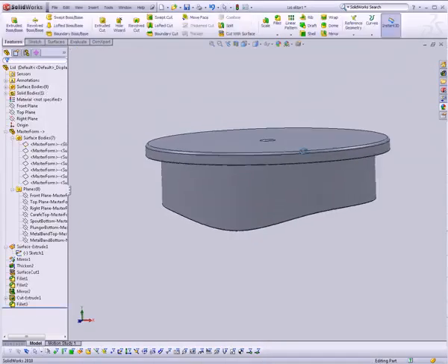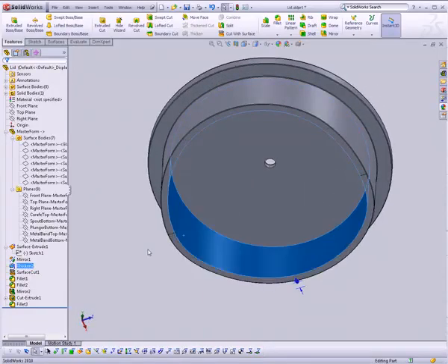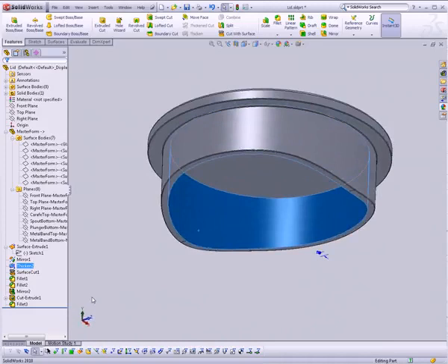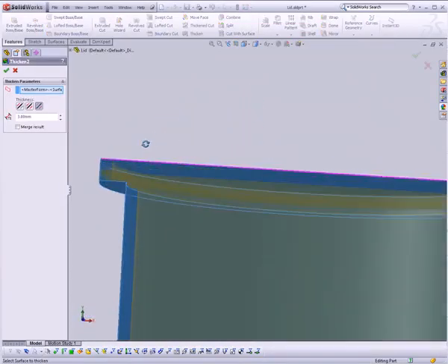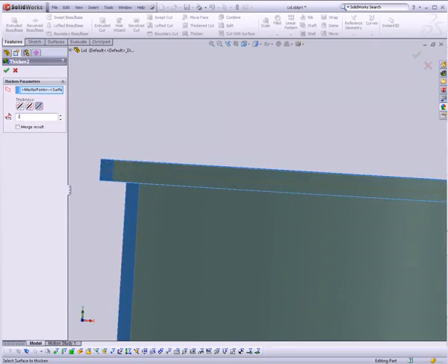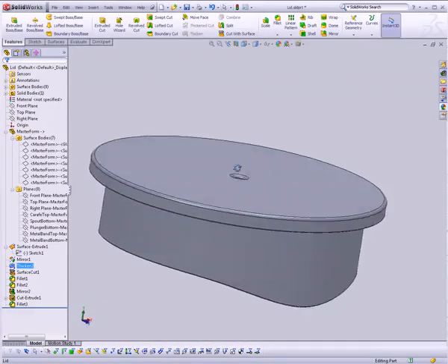Now also, the wall thickness is too thick here, and if I make it any thinner in my thicken feature, like if I change this to 2 millimeters for instance, or 1 millimeter for that matter, just to make the point. So we make it 1 millimeter, then if we look in here, we can look at a cross-section by clicking on cross-section view up here at the top.